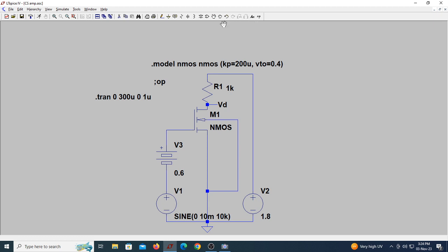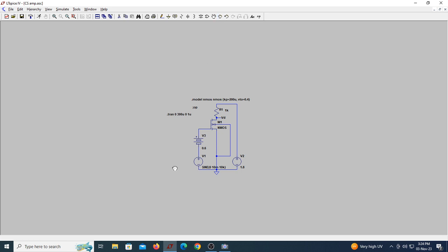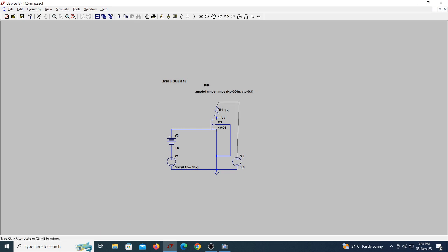Now what I'll do, I will slightly minimize this. I will pull this slightly this side so that I can comfortably do the things. I will pull this also. Okay, now let me take two resistors such that I can eliminate this. Okay, how do I eliminate? This is my scissor, or you can press this F5, function 5. I have taken out this, then let me short it. So you have a wire, F3.